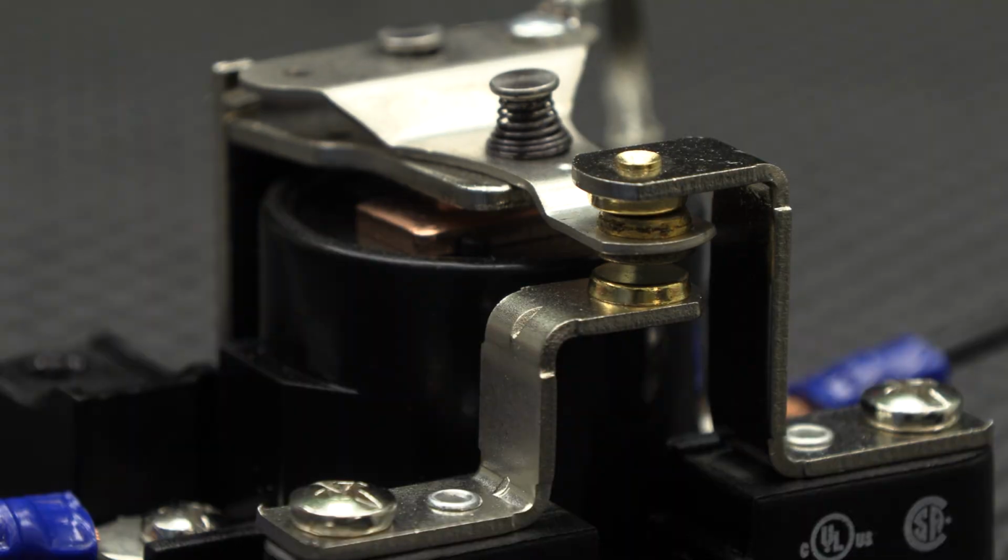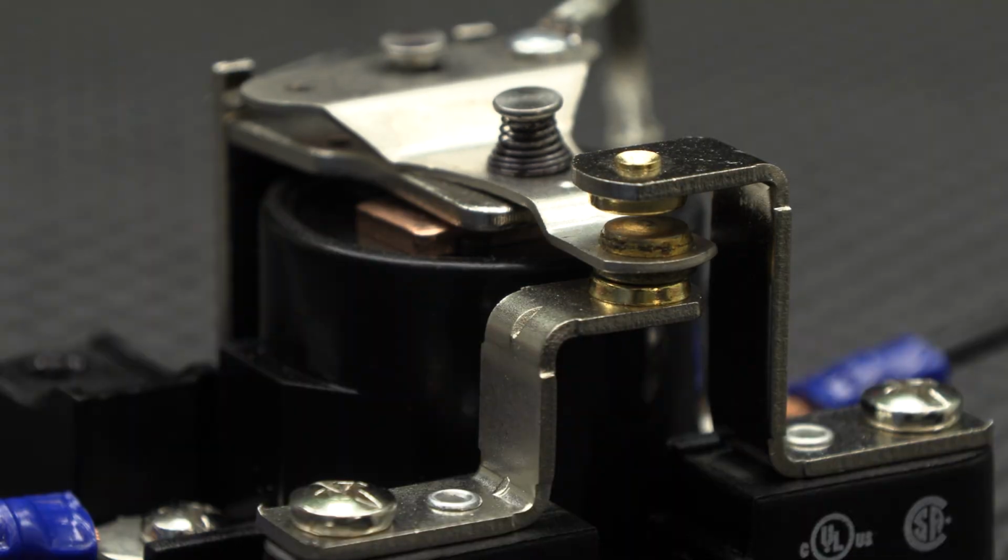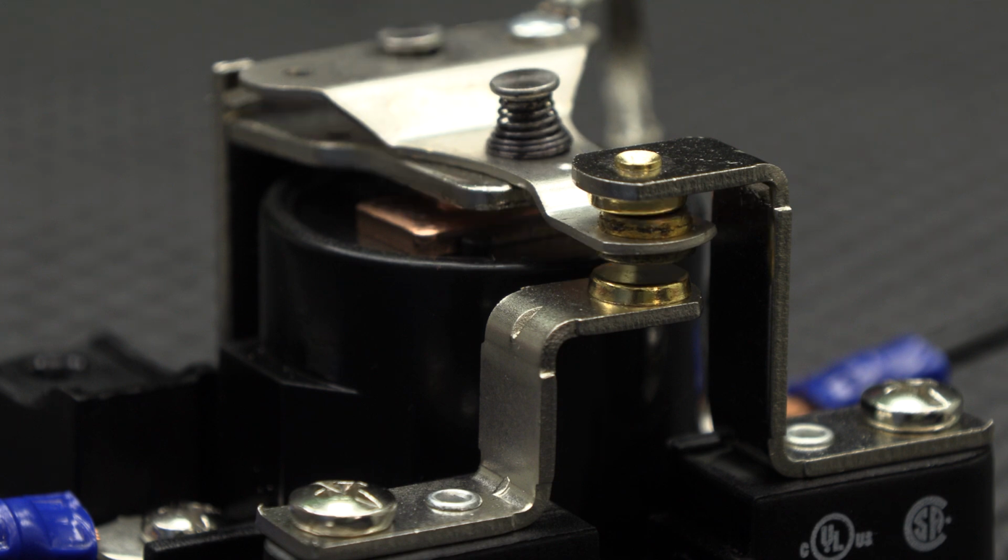The contacts are burned. Relays have contacts that open and close. And over time, they burn or they oxidize. Or they weld shut. They burn open. They're problems. And think about this, folks. We'd have hundreds of them. Some cabinets had 1,000 relays. So these wiring schematics got to be very extensive.